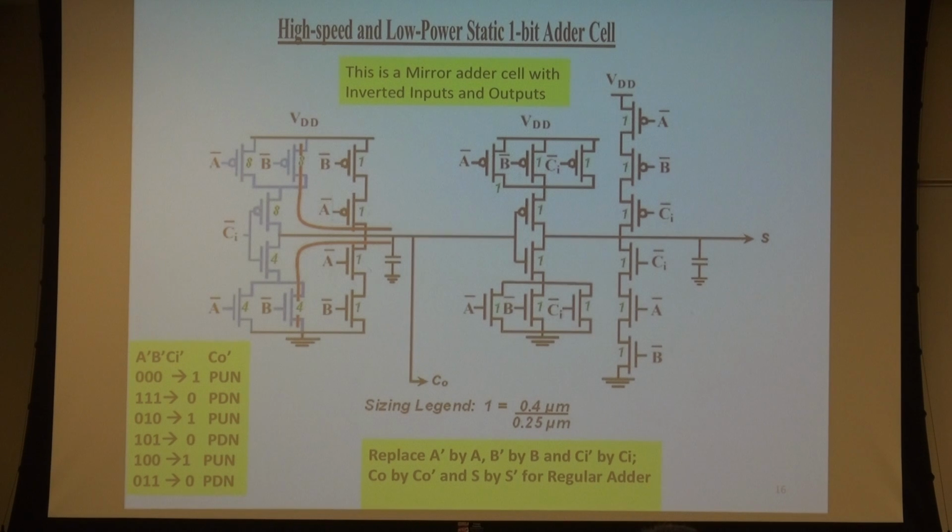So this is how a good circuit designer will be designing the circuit. They will not only do the logic analysis, they will do the circuit schematic analysis, then together they will do it by removing the inverters, and then they will go back and resize the transistors, looking at the data patterns, the probability of the data patterns, the probability of the signal